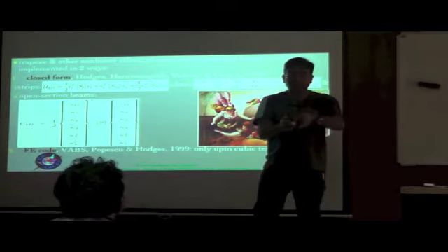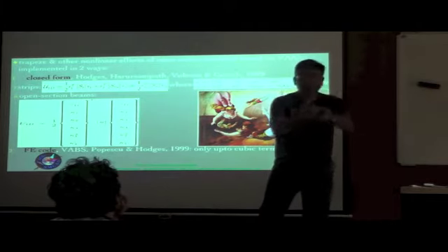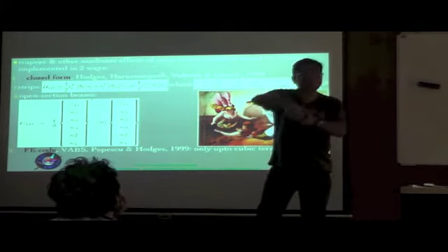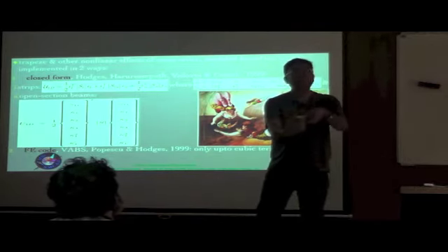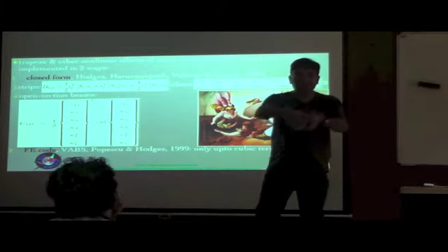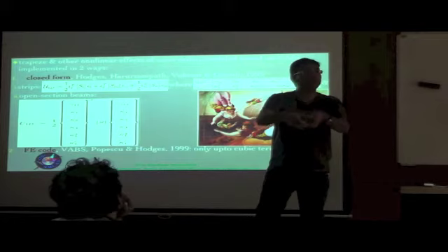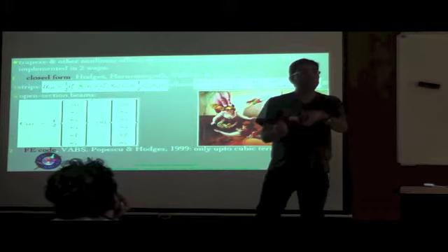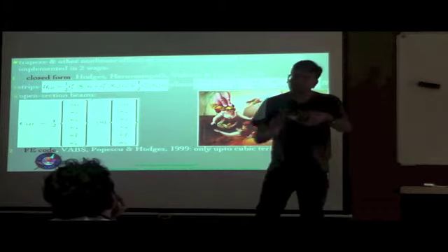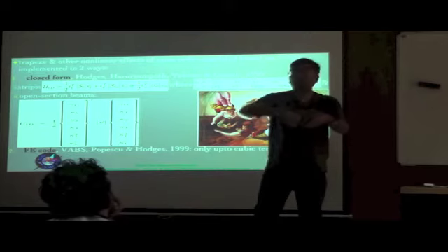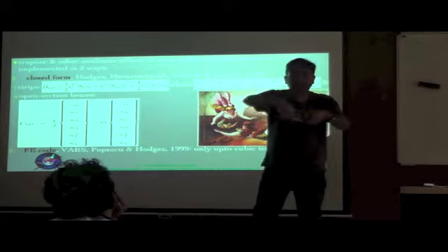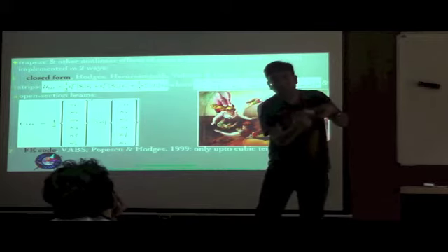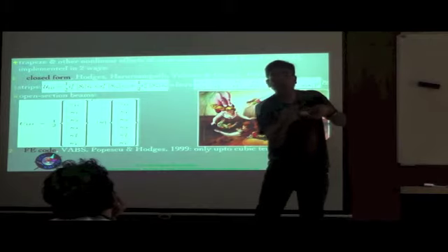You basically see that now, whereas in this case you had this curvature being much larger compared to this curvature, once this comes in here, you see that this bending stiffness is now going to be provided by this component, whereas this bending stiffness is primarily going to be provided by this component, and therefore in both these directions the bending curvatures are of the same order of magnitude. One is not much larger than the other, but still you will have the torsional softness because it is an open cross section, and the way open cross sections react to a torque is through a shear flow which tends to turn around itself in each of the walls.